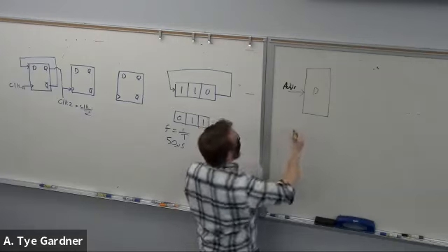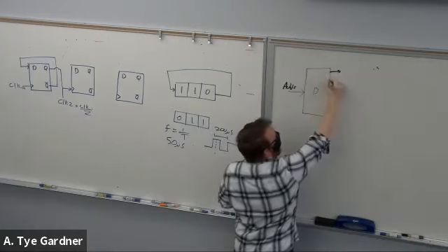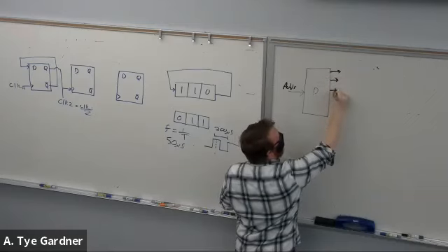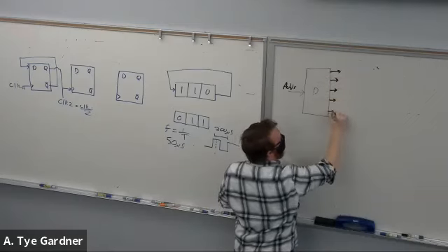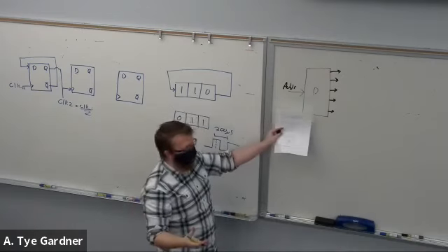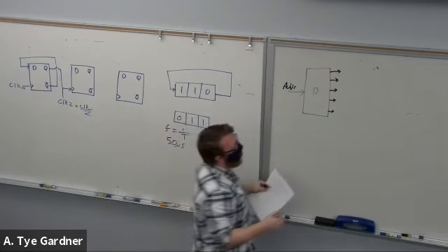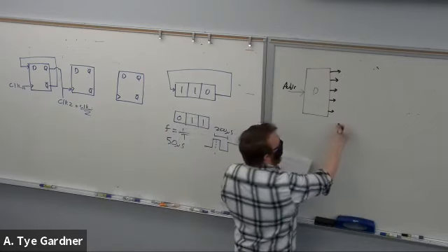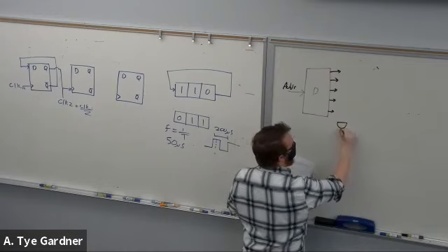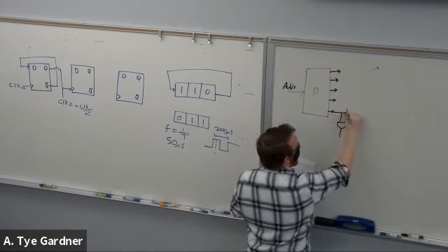What the decoder does is take the address and assert one line of the decoder. It's an unmux, a demux. And then these lines, in the case of addressable memory, just have an AND gate in one of the cases, the example that I use.